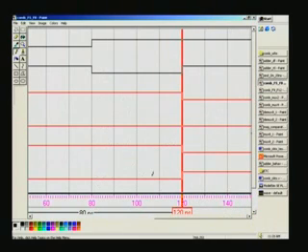And for this case, it is 1 1. In the 1 1 case, exclusive OR is 1 plus 1, 0. So actually the sum bit is 0. We are looking at only the sum, not the carry, and that is what is here. It is 0. 1 plus 1 is 0 in exclusive OR, and the inversion of that, exclusive NOR, is 1 here. And we have checked up to F8, so we will remove this window.